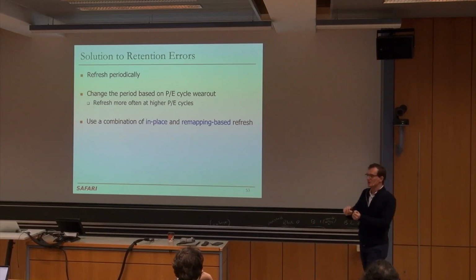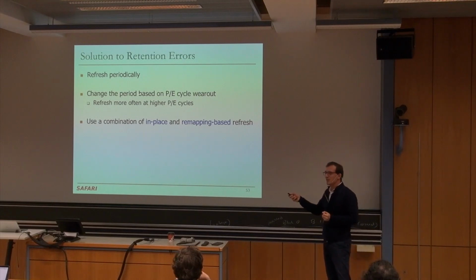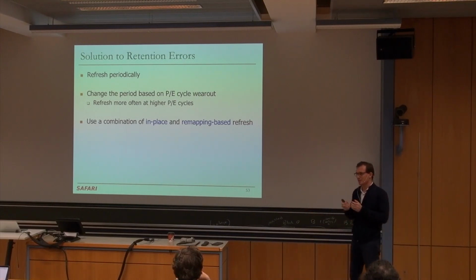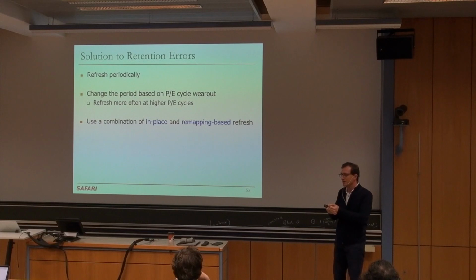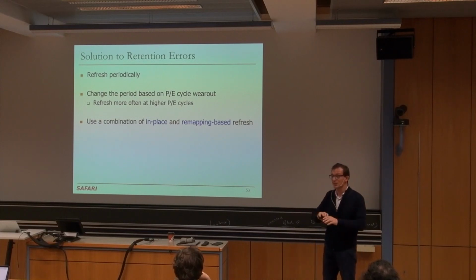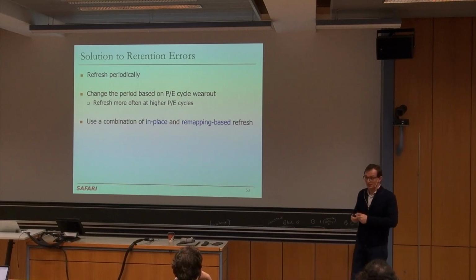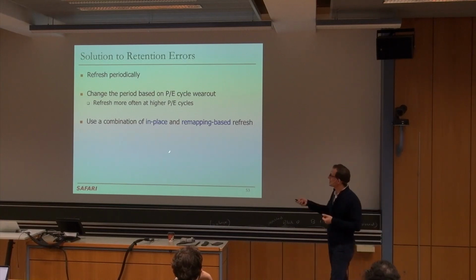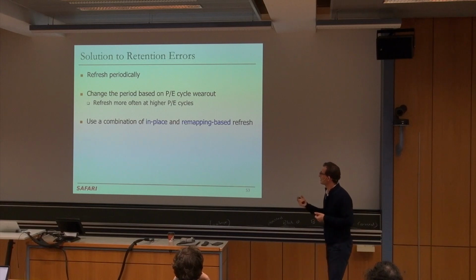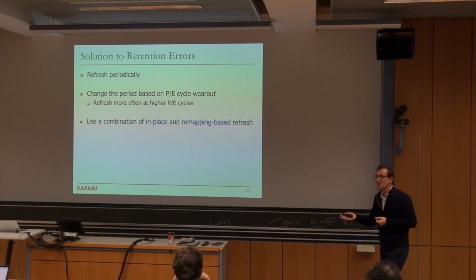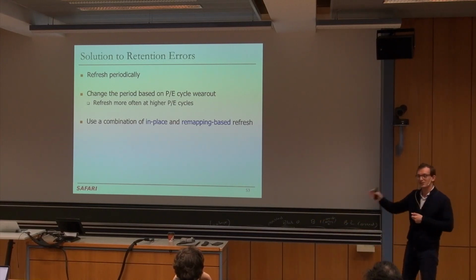It turns out you can actually do this in place, meaning that whenever you do programming of a flash page, you can increase the voltage, but you cannot reduce the voltage. In refresh you need to increase the voltage, which means that you can actually program that particular page you need to refresh in place without moving it somewhere else.